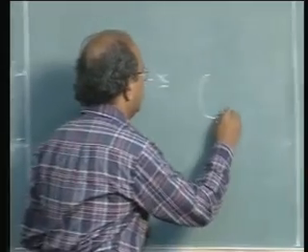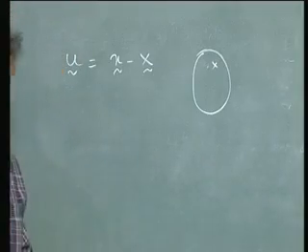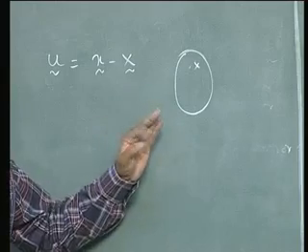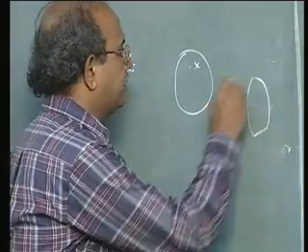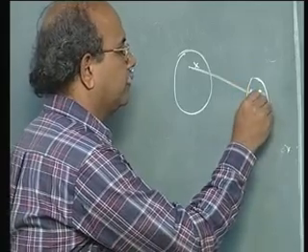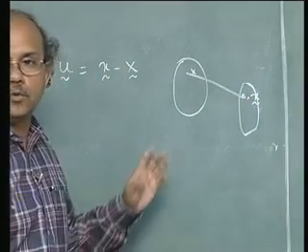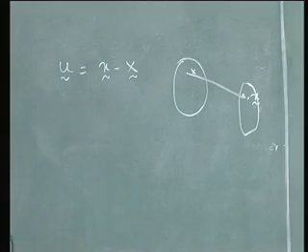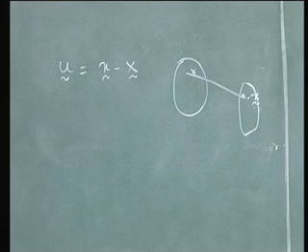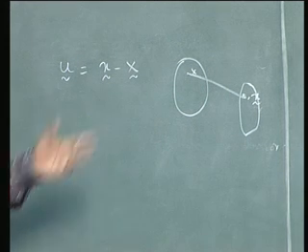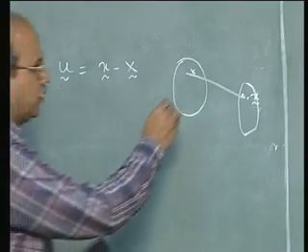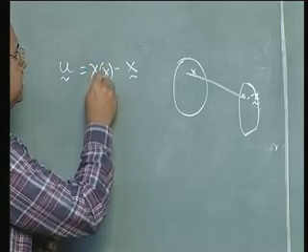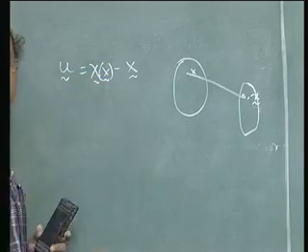So in other words, if that is the body where it's capital X, Lagrangian frame of reference, and we start here, say for example, most of the time as I said, reference coordinates, and we go to this point x, let u is equal to x minus capital X. Now this is fine as long as both systems of coordinates that you use are the same, or else you can also write that as chi of X minus X.